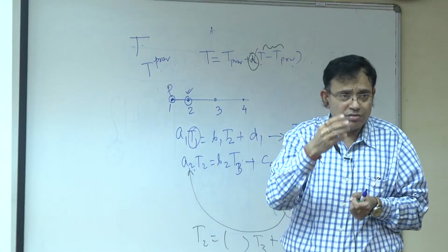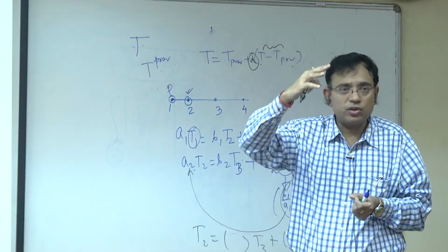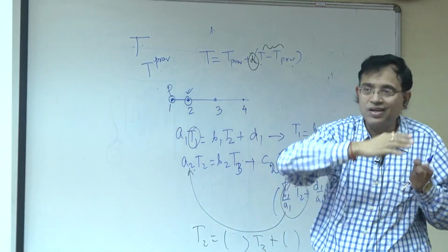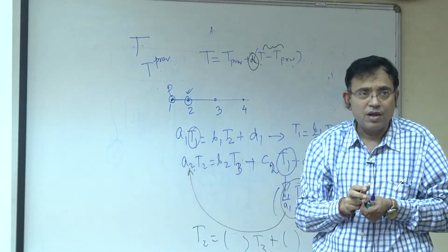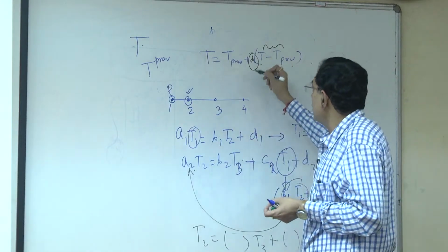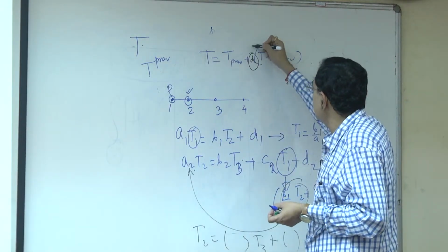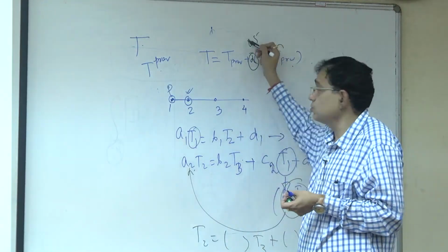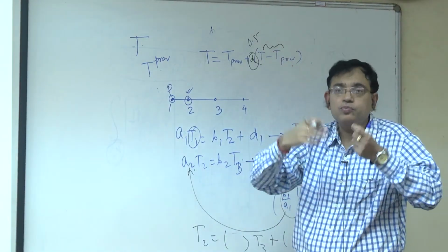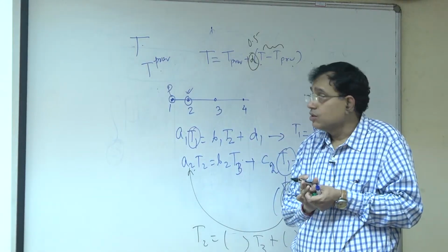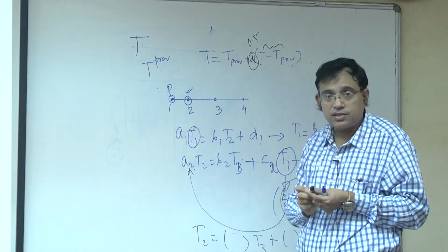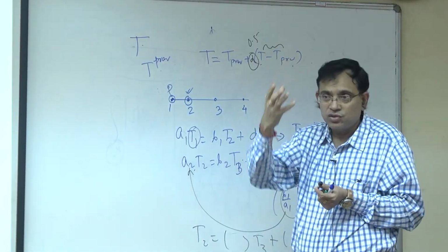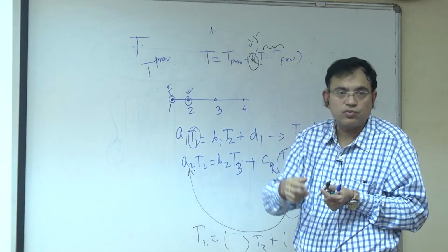If it is going much out of control, you use a small number, but not too small, because then you will never be able to reach convergence. Something reasonable, maybe 0.5, I am just giving an example. But there is no such rule; you have to adjust it from problem to problem. This is called a relaxation factor. Sometimes you can also use it greater than 1, when it is slow and you want to accelerate it. Depending on that, you call it under-relaxation or over-relaxation.